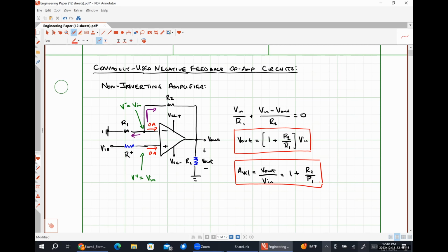Why might we want a unity gain buffer? Why would that be used? You can pull however much current you need. Exactly right. So sometimes we're going to be asked to amplify signals from transducers that aren't capable of developing a lot of current, right? So for those of you that go into, well, all of you I think are electrical engineers right now, but some of you might do senior design projects where you work with, say, biomedical engineering students or something like that, trying to help them set things up.